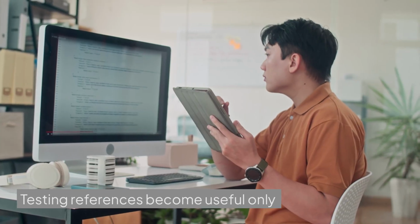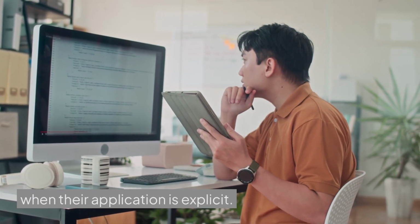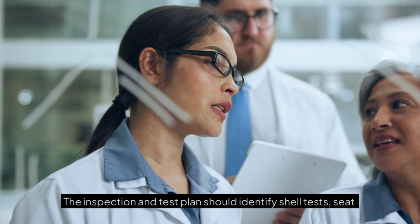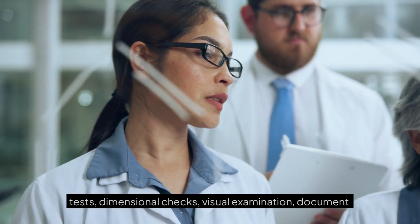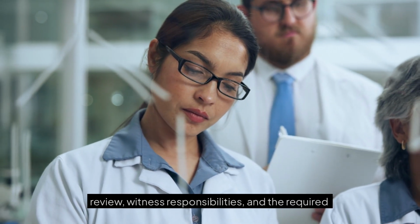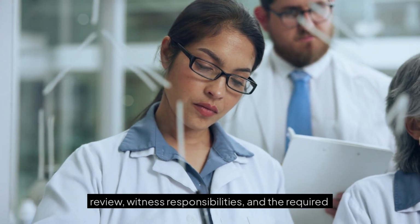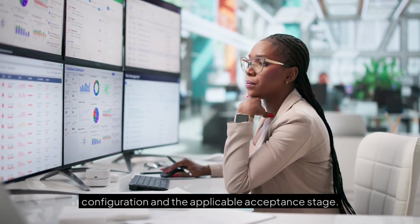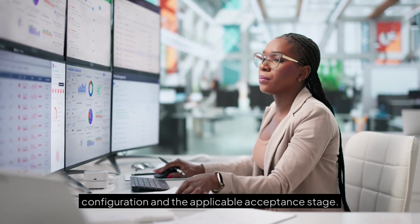Testing references become useful only when their application is explicit. The inspection and test plan should identify shell tests, seat tests, dimensional checks, visual examination, document review, witness responsibilities, and the required acceptance format. Test reports must be traceable to the approved configuration and the applicable acceptance stage.